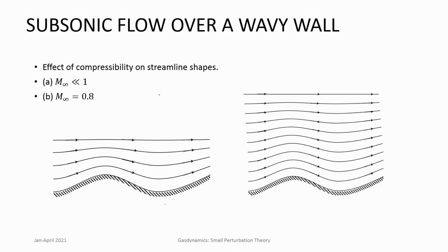You see that there is a term e power something here. So, e power and a function of y, some say g of y or q of y, not to confuse. So, e power minus q of y. So, this function reduces the amplitude as you go away from the wall. So, that at a certain distance the effect of the wall is completely forgotten. Okay. So, if you look at the streamlines, they look like this. Near the wall they follow the wall very much, but as you go further and further away they change, and then again they come back to being similar to the streamline itself.